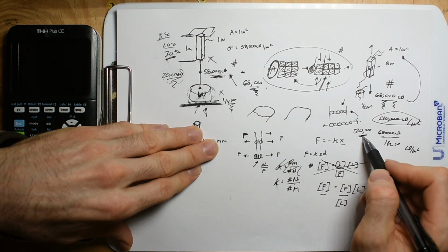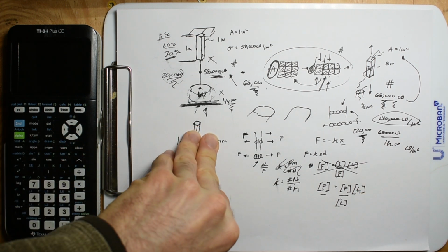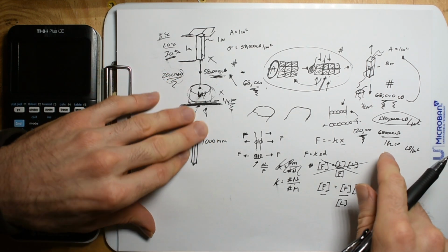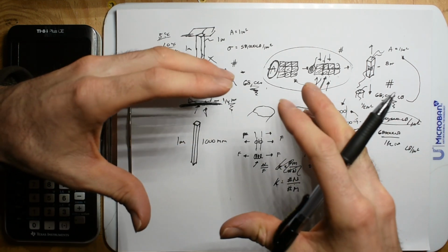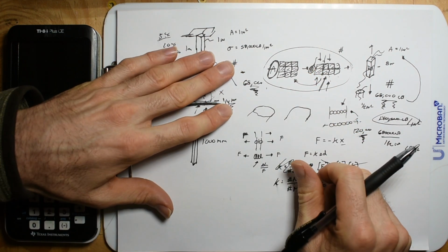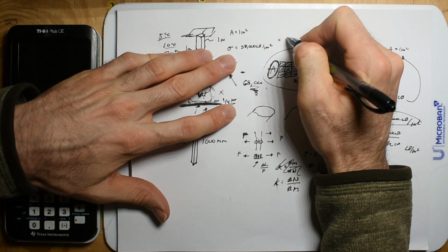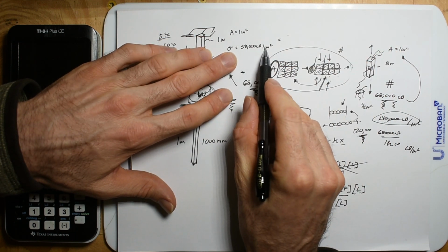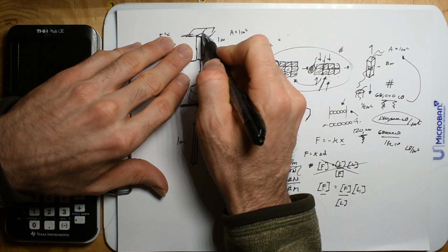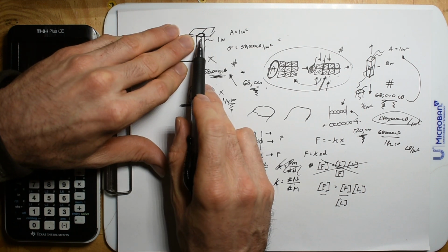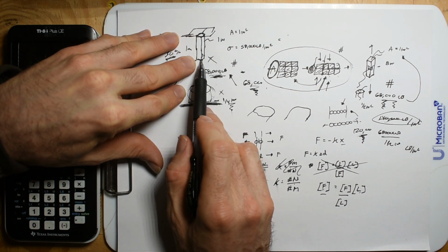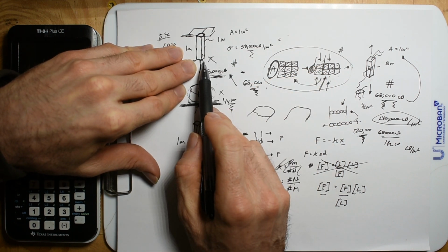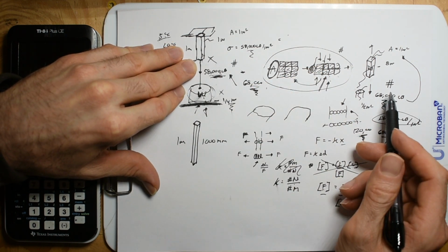then this brings up the concept that the only way to talk about the strength of a material is in units of pressure, PSI. This is 58,000 pounds per square inch. It means if I have a surface area of an inch, in this 1-inch square rod, I can pull 58,000 pounds on it.